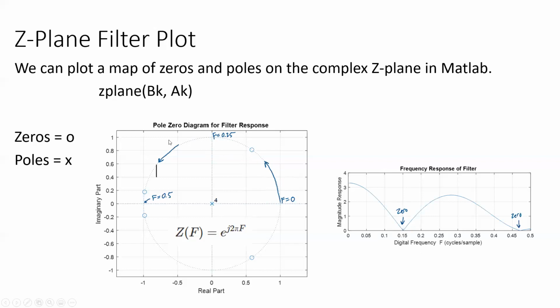And then as we get to the higher frequencies, maybe I don't want that, so I'll remove the zeros here. So it gives you a way to just place zeros just by looking at this thing. And then from those poles and zeros, you can get back your BKs and your AKs, and then you can eventually get to a difference equation if you want that. So pretty powerful tool. It allows you to construct kind of whatever filter you want, more or less.